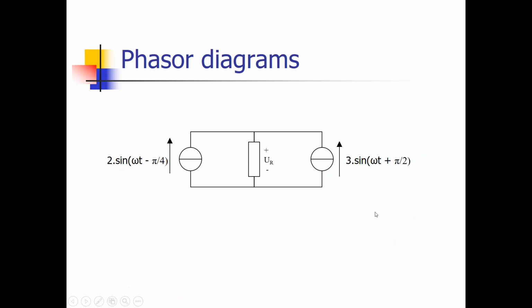So knowing that, we can redefine this problem to a problem with two phasors, and then add up the phasors and look at the combined amplitude of the new current, the new amplitude and the new phase angle of this current with the x-axis.